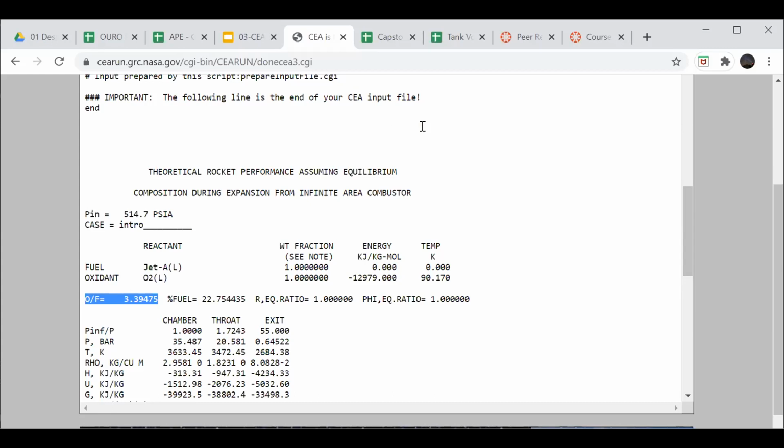And then for Carrie's question, phi is basically the ratio of whatever OF ratio you're using to the stoichiometric ratio. So in this case, where phi equals 1, your stoichiometric ratio for combustion is this. And if phi is greater than 1, oh boy, I don't remember if you're fuel rich or ox rich, but this ratio is slightly off in one direction, and if it's a little less than 1, it's slightly off in the other direction. Whatever direction that is depends on how phi is actually defined. I don't remember if it's OF or fuel to ox. There's a lot of ratios to remember, but yeah.